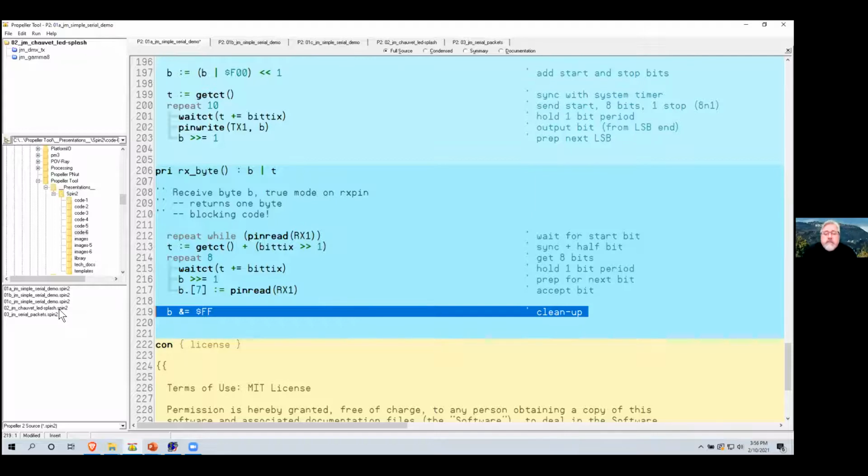So this works. And like I said, I'm very easily entertained. It made me laugh out loud, I kid you not, when this code, which is interpreted Spin, would do 230K baud. Because on the P1, I think the top end, and you had to be a little careful not to add any fluff to the code, which I sometimes do, you could do 19.2K baud at 80 megahertz.